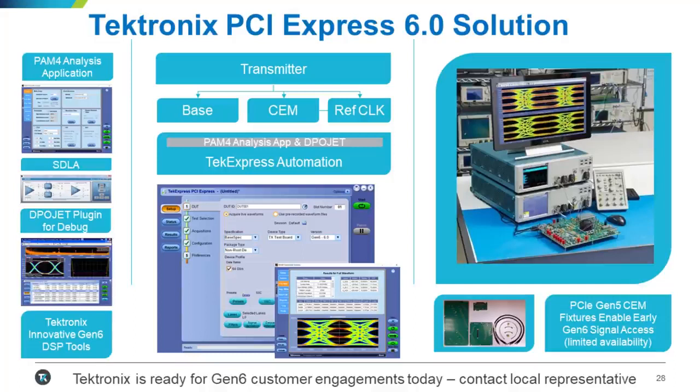The nice thing is that our Nyquist has remained the same, and there's also a desire to keep the bandwidth at a reasonable level to address noise. So generally, what we're seeing is a 50 gigahertz scope bandwidth requirement, and we really looked at it for base testing so far.